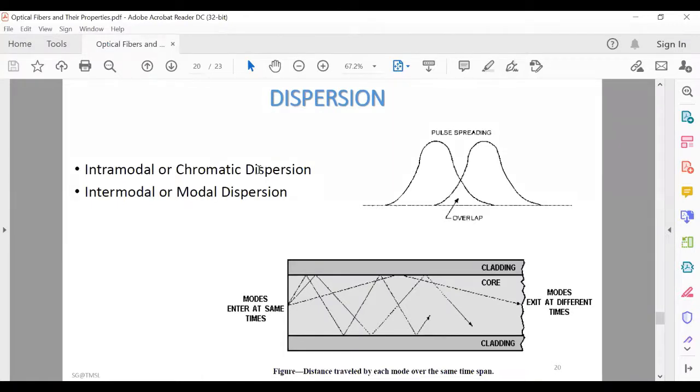Waveguide dispersion and material dispersion are basically separate properties. In multi-mode fiber, waveguide dispersion is generally small compared to material dispersion, and it is usually neglected. But in the case of single mode fibers, material and waveguide dispersion are interrelated. The total dispersion present in single mode fibers may be minimized by trading material and waveguide properties depending on the wavelength of operation.